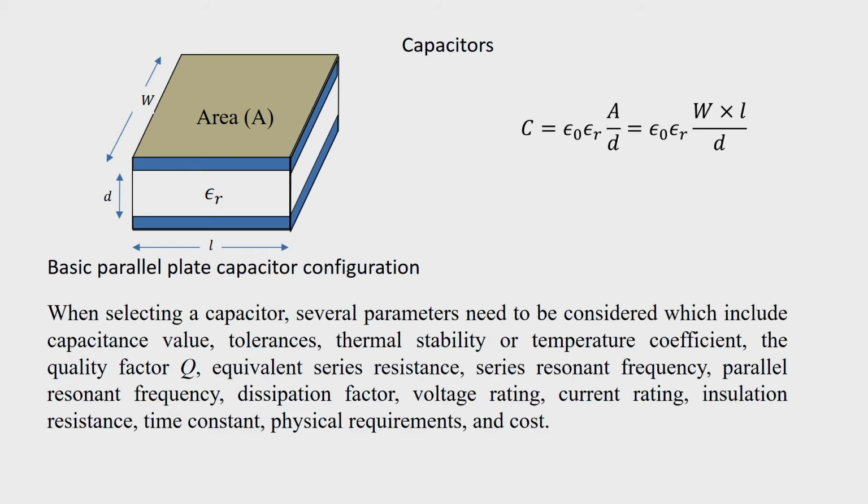When we select a capacitor, several parameters need to be considered, which include, first of all, of course, the value of the capacitor, the capacitance value we need. Then the tolerances, thermal stability and temperature coefficient. The quality factor, the capacitor is to store charge, and quality factor will determine how much energy is stored and how much power is dissipated.